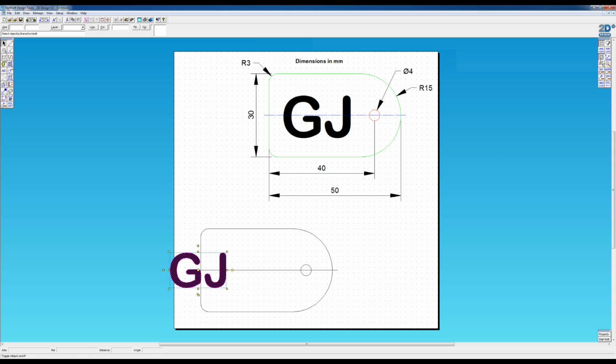I'm going to turn attach off, and then we're going to use this new tool called Radial Lock. A Radial Lock in its standard mode will lock any movement to horizontal, left to right, 45 degrees, or vertical. So essentially it's locking in 45-degree chunks.